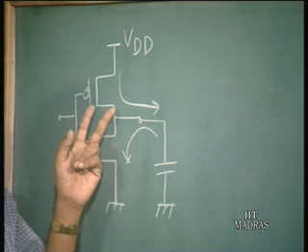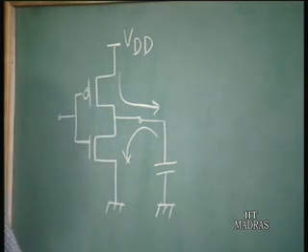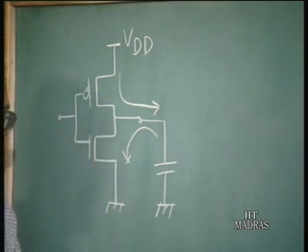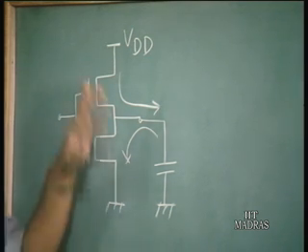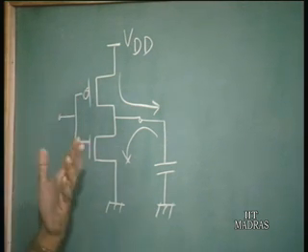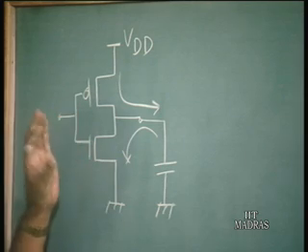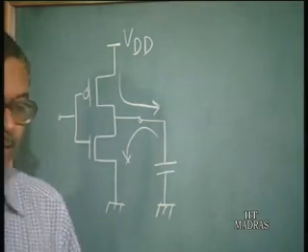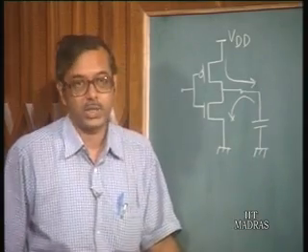Of course, here one must also point out that with the same dimensions for the NMOS and the PMOS transistors, the PMOS would have a lower current because of the lower mobility of holes. So, in fact, if one has to go for equal on and off times, then one has to increase the width of the PMOS transistor. But that is a small disadvantage. The major advantages of CMOS are that we have 0 static power dissipation, and also we can have almost minimum size transistors, and also while switching on and off, since the two currents do not clash, one can have fast switching also.